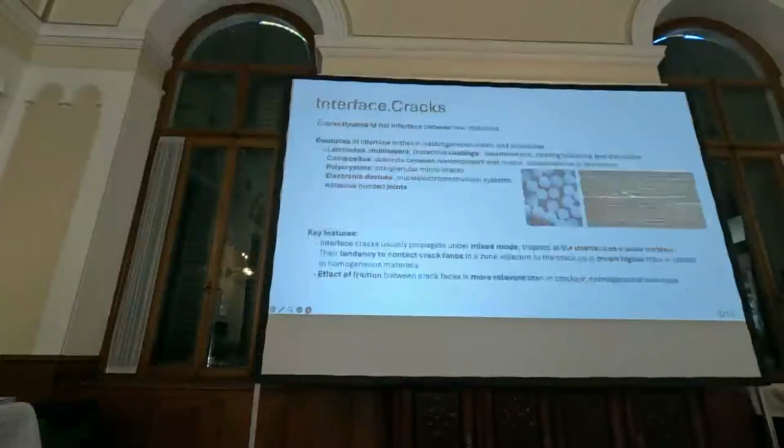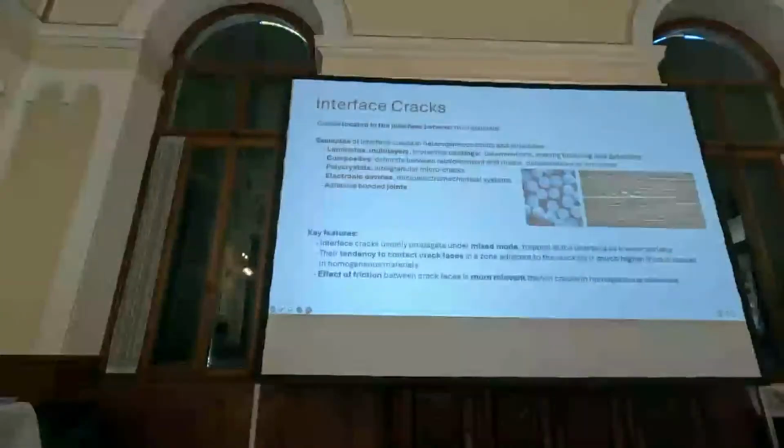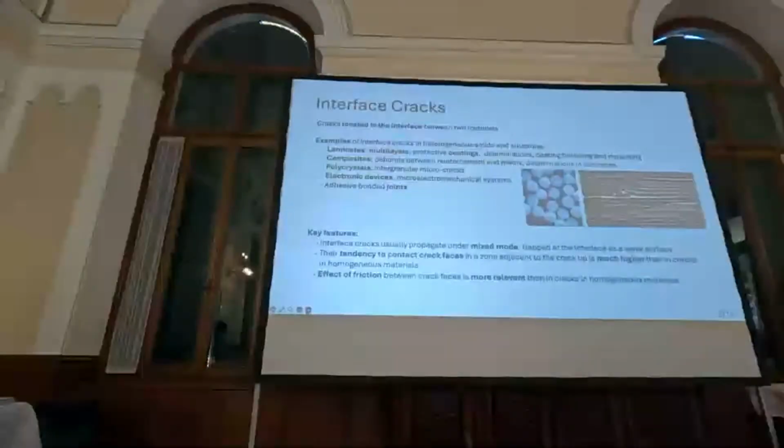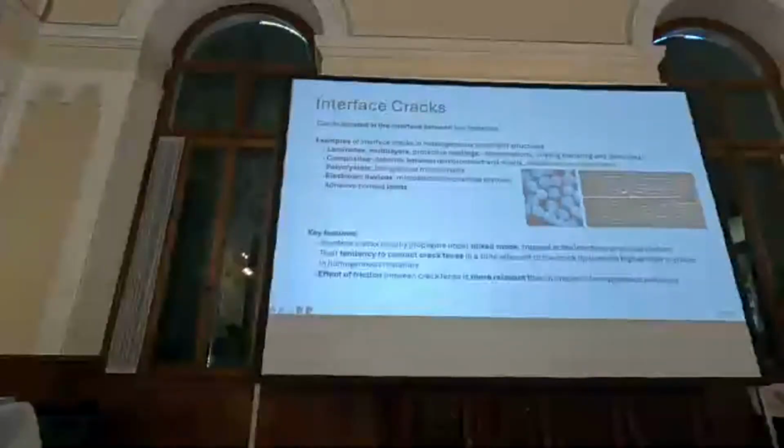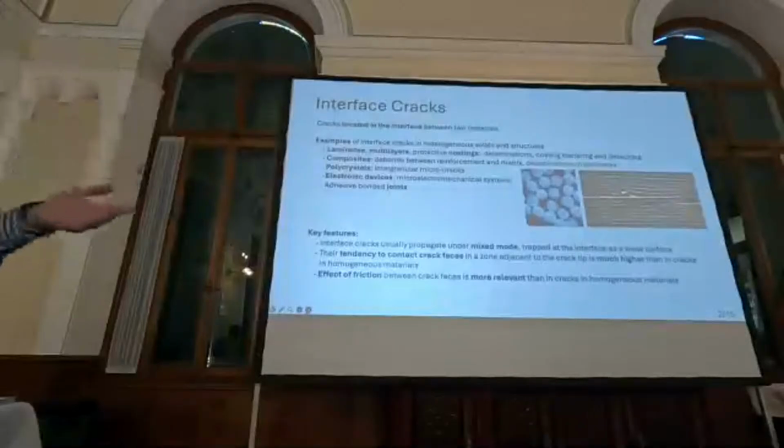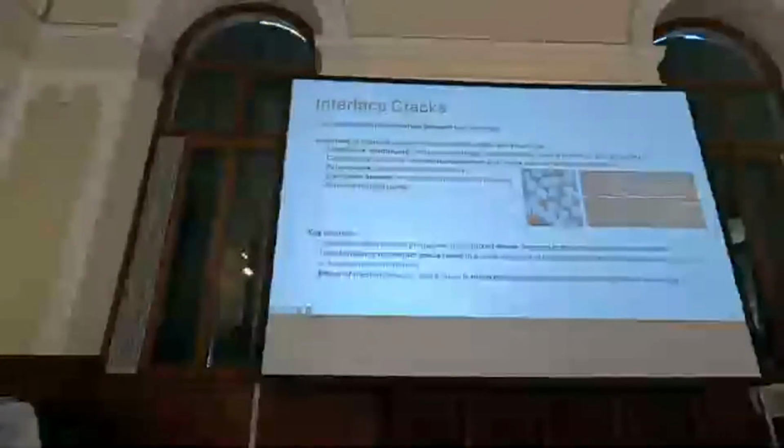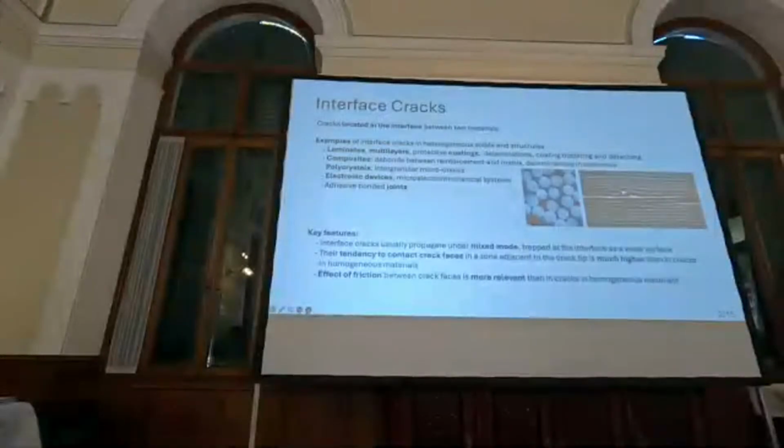We solved many problems of this kind, for example, for this interface crack, where we have no contact zone or it's very small, which cannot be detected by the numerical method. And then if the crack is larger, we can have a relatively large contact zone. So the contact zone can increase depending on the size of the interface crack, the position with respect to the load, etc.